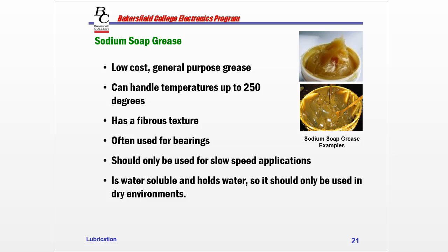And when you do, what are we going to have that we're trying to prevent with lubrication? Metal to metal contact. Those bearings will wear prematurely and fail, and could actually heat up enough to fuse to the spindle and actually heat that spindle to where it just falls off the trailer. I've actually seen trailers on the side of the highway where the axle is actually broken off and the bearing race is actually fused to the axle because it overheated due to the lack of lubricant.